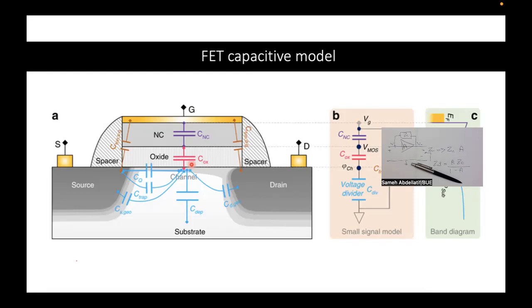So you can act to decrease the value of the parasitic capacitance by fabrication parameters related to the oxide thickness or the oxide dielectric constant or whatever. On the other hand, by a way or another, you will still have a parasitic capacitance.